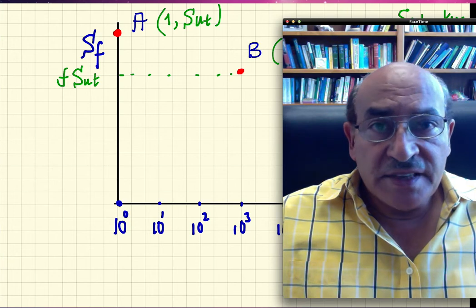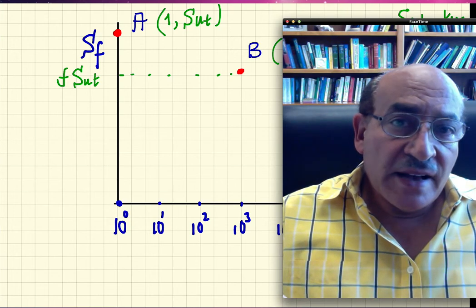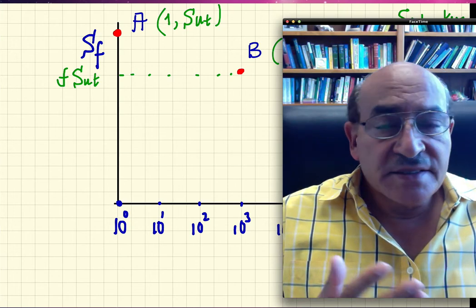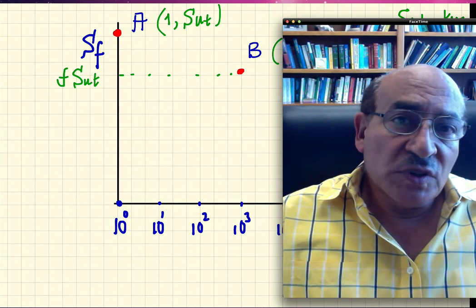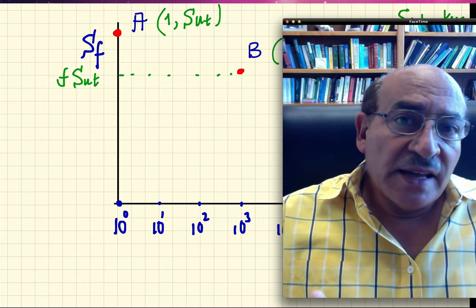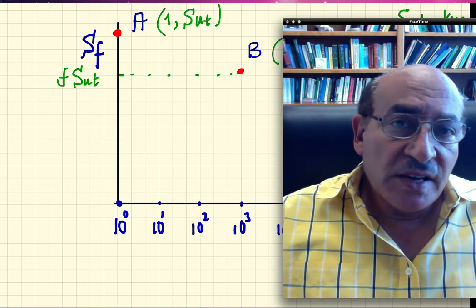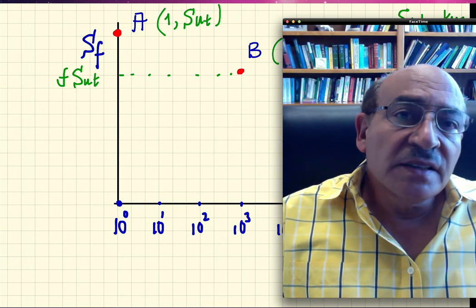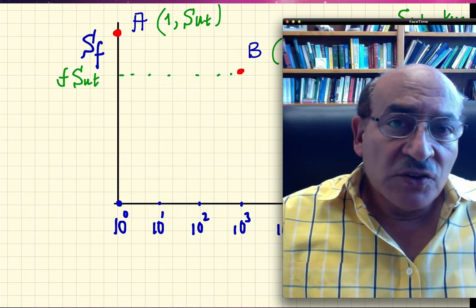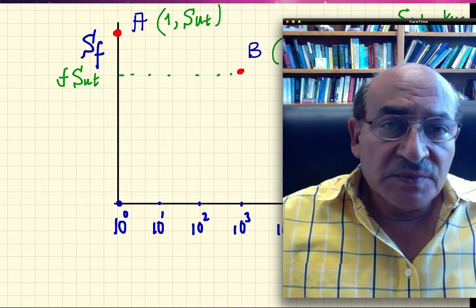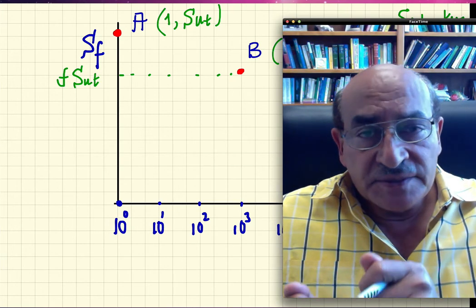steels, raw steels. So if you have cast steels, it will be less. If you have maybe cold work steels, it will be higher. And we have this correlation. So I will show you a figure that relates the endurance limit to the ultimate strength. So we're going to open up the manual, get the ultimate strength, use this correlation to get the endurance.